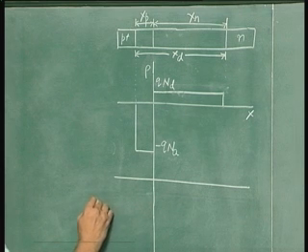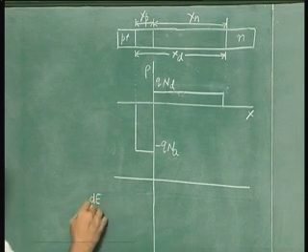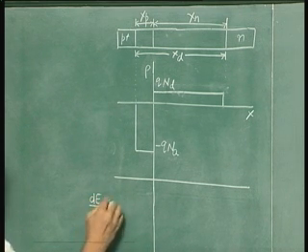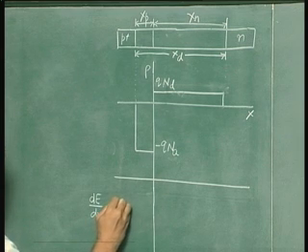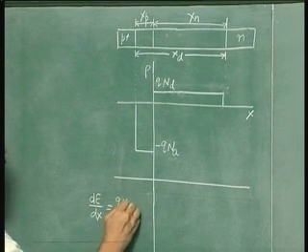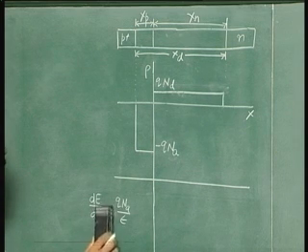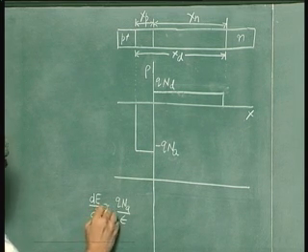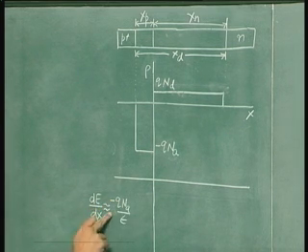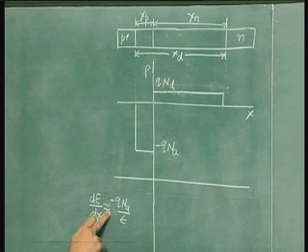that dE by dx is equal to rho by epsilon, that is minus q Na by epsilon, approximately equal to, because this is a depletion approximation that we are using.